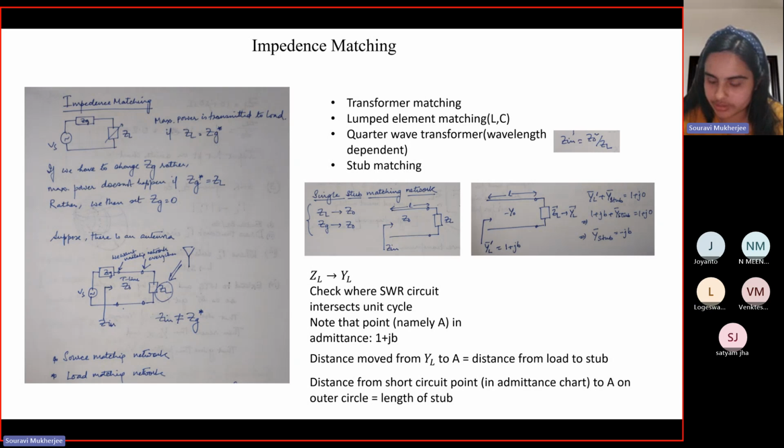So basically what you are telling is, if you say that your SWR is 1, that means there is no reflection. That means the characteristic impedance of your transmission line should match with the load at the load end. So Z0 should be equal to ZL. If your ZL is 1 plus 0.2J, then your Z0 should also be equal to 1 plus 0.2J. Okay, ma'am. That is it.